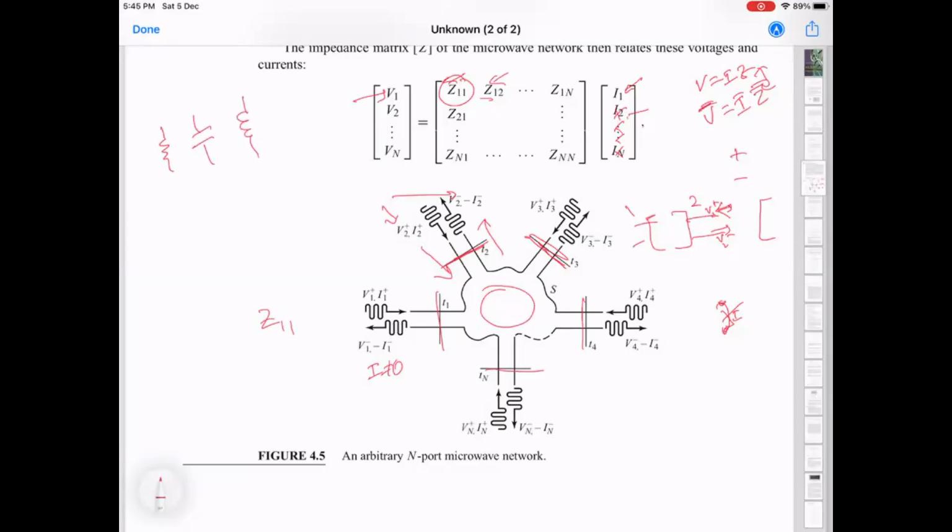And if you're constructing some complicated circuit, which we are now calling a network, which again could be just a piece of transmission line where there's an array of L's and C's, or something else, as we will see in just a little bit, the thing we actually know about these circuits is Ohm's law for each one of them. So the impedance is something we know. I know how to write down the impedance of L, right? That is just omega L. Similarly, I know how to write down the impedance of C.